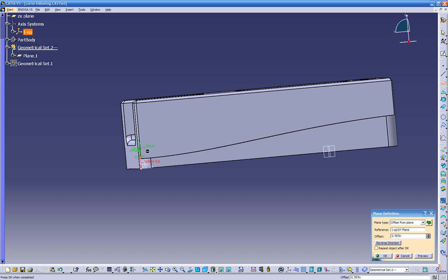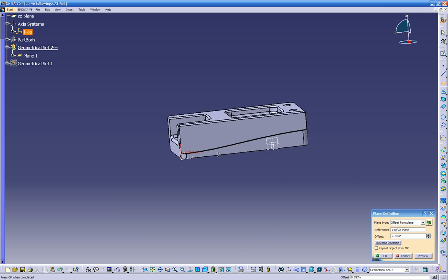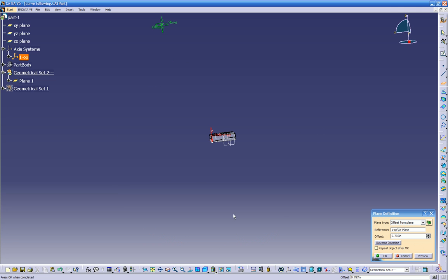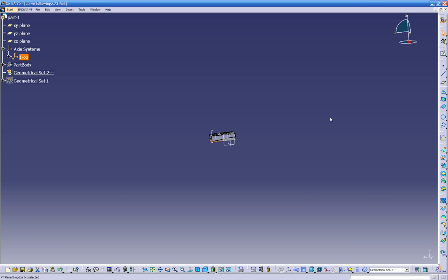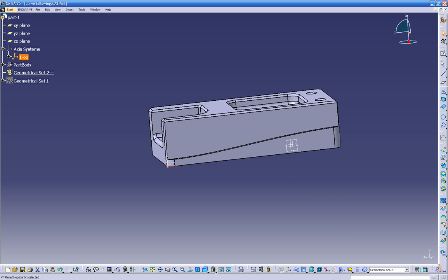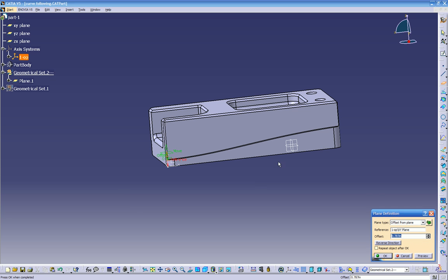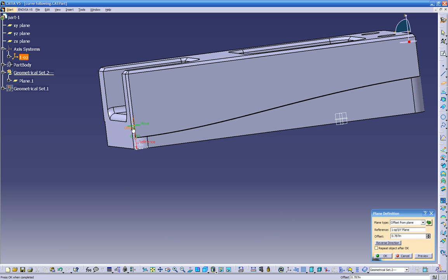Okay, so it says from here it's 787, so we can move it up, or we can offset it. So we're going to cancel this right now. I'm just going to put an offset instead of moving. So just click back on it. So instead of moving, you just go to offset, and that way it goes along the line.